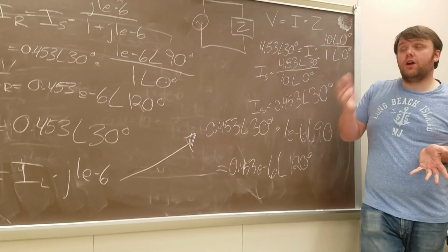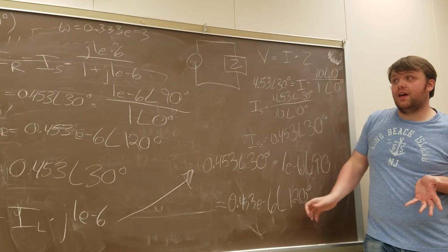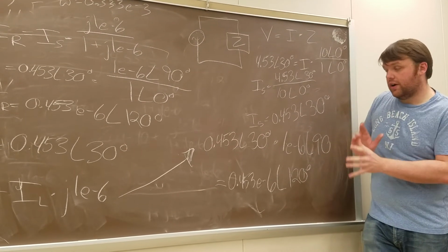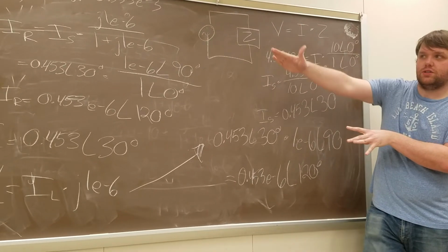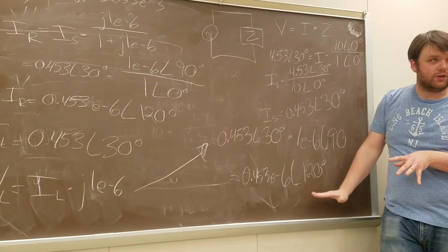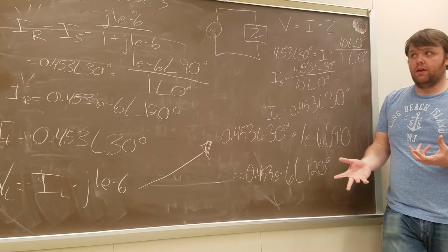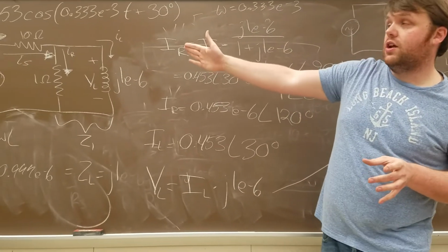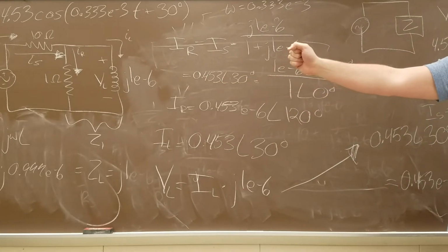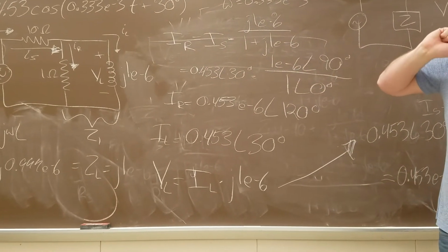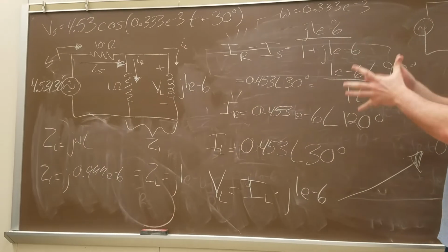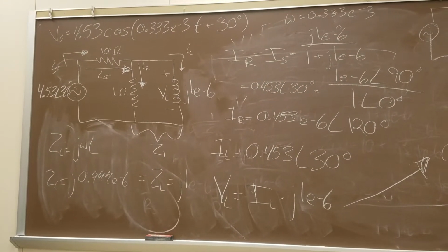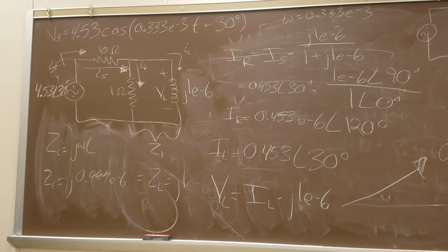And it gets all of the current. So what this is actually telling us is that the voltage drop across the resistor is going to be equivalent to the voltage drop across the inductor because they're parallel, right? So almost all of the voltage in this circuit is dropping across that 10 ohm resistor, right? Because I have 10 ohms connected in series with 1 and an incredibly small number as far as the magnitudes go. Okay, so that's number 10.